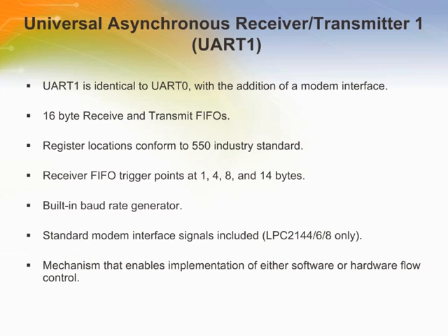The UART1 receiver block, U1RX, monitors the serial input line, RxD1, for valid input. The UART1 RX shift register, U1RSR, accepts valid characters via RxD1. After a valid character is assembled in the U1RSR, it is passed to the UART1 RX buffer register FIFO to await access by the CPU or host via the generic host interface.